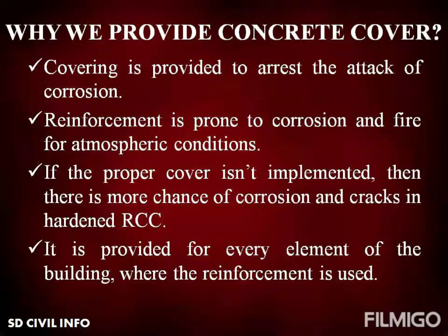Let us see why we should provide concrete cover. In reinforced concrete, covering is provided to arrest the attack of corrosion, as reinforcement is prone to corrosion and fire under several atmospheric conditions. If the cover is not implemented properly, there is more chance of corrosion, and in hardened reinforced cement concrete, cracks may form. Therefore, concrete cover is to be provided for every element of the building where reinforcement is used.